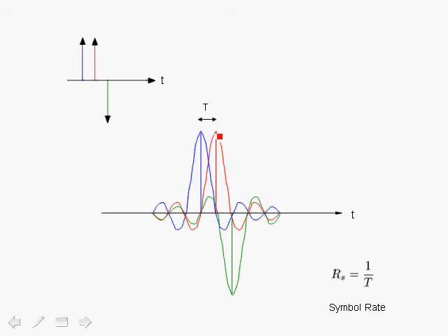So if we sample the signal at its peak, we will have zero intersymbol interference, for example, as shown over here. Now obviously if there's jitter in the sampling process, jitter in the clock, or errors in the timing recovery, then we will get a large amount of intersymbol interference, and it is only zero when we sample at the optimum time at the peak, as shown over here.